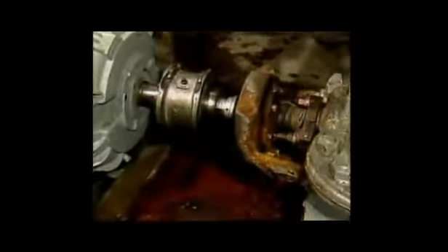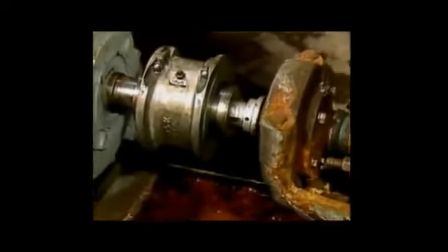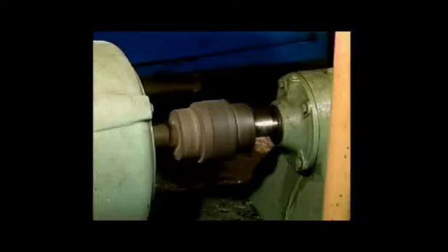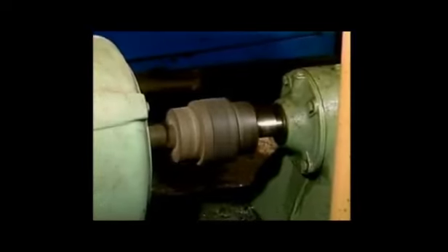Another piece of auxiliary equipment is a coupling. A coupling is a device that connects the driver's shaft to the pump shaft. Couplings can be divided into 2 categories: fixed couplings and variable couplings. When a fixed coupling is used, the speed of the pump is fixed by the speed of the driver. To change the speed of the pump, the speed of the driver has to be changed. On the other hand, when a variable coupling is used, the speed of the pump can be changed without changing the speed of the driver.